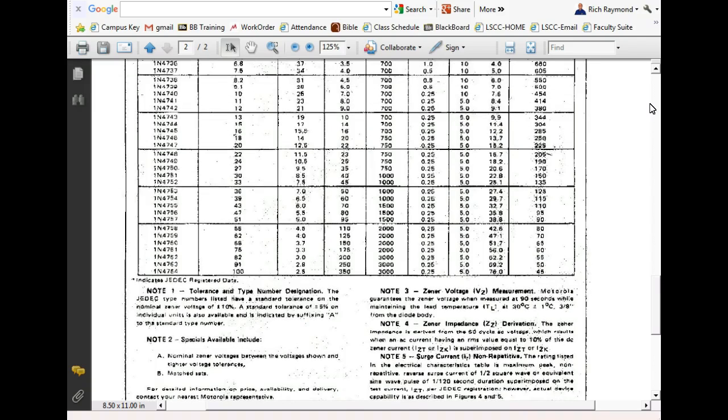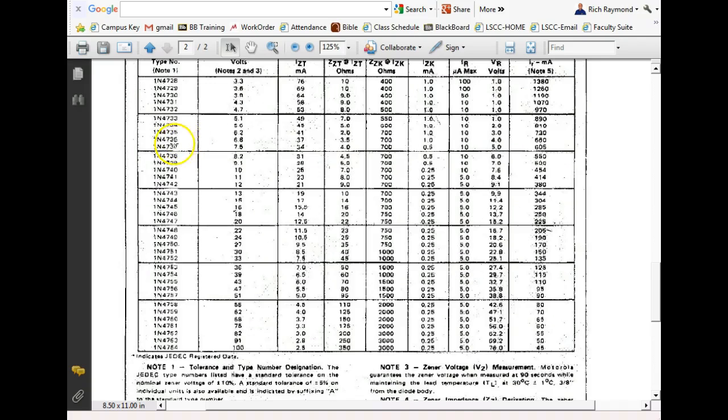Yeah, we got some of these. Let me pause this and go. 35 is a 6.2 volt Zener, 1 watt Zener. This is a 4744. So 4744 would be a 16 volt Zener, or 15 volt Zener. 4742, what would that be? 12 volt Zener. Are you okay? And they look just like diodes. These are a little bigger because they're bigger diodes. You know, you can't tell them.